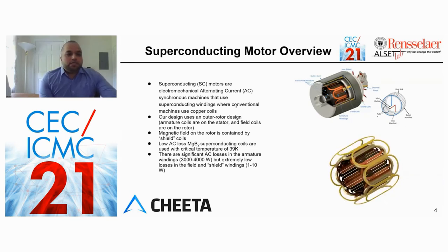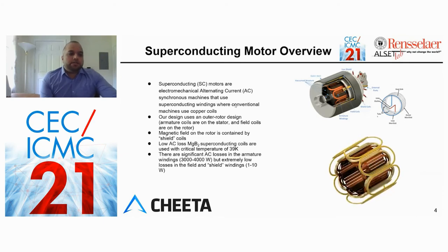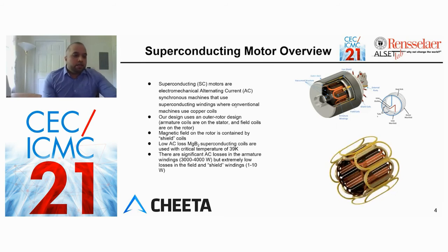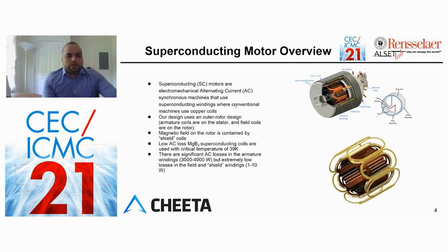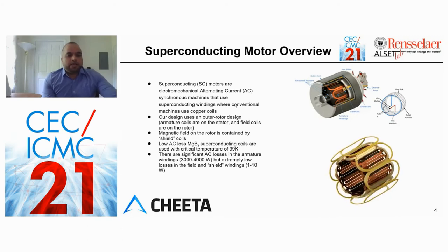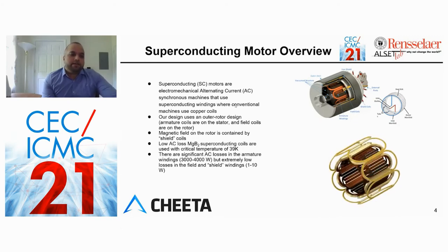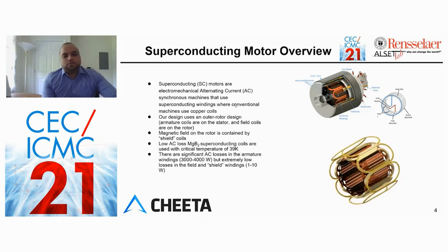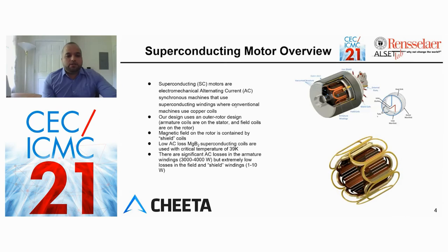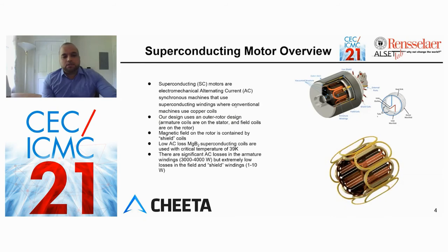CHEETAH uses an outer rotor design where the armature coils are on the stator and the field coils are on the rotor. The magnetic field on the rotor is contained by the shield coils. This is done to avoid usage of bulky iron shielding. Low AC loss MgB2 superconducting coils from Hypertech are used that have a critical temperature of 39 degrees Kelvin. Though lesser than other superconductors, the losses are still in the order of around 4 kilowatts. Minimal losses of 1 to 10 watts are also observed in the field and shield windings, but for the cooling system design purpose, the focus remains on the armature coils.